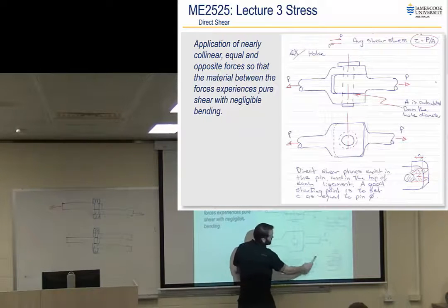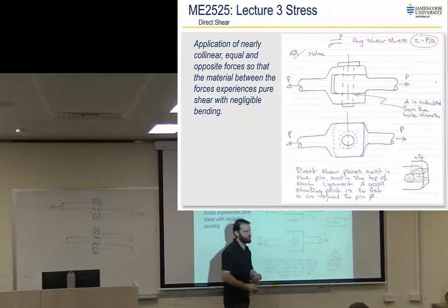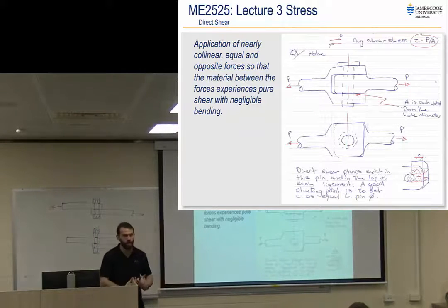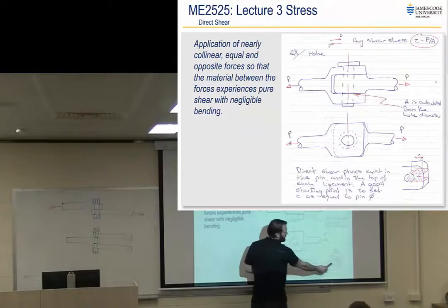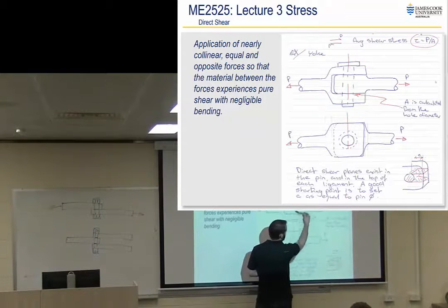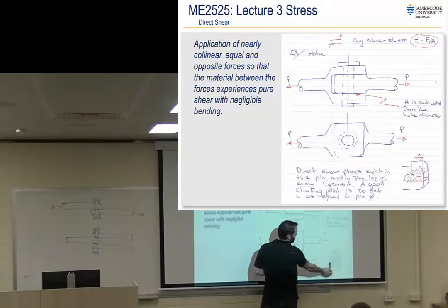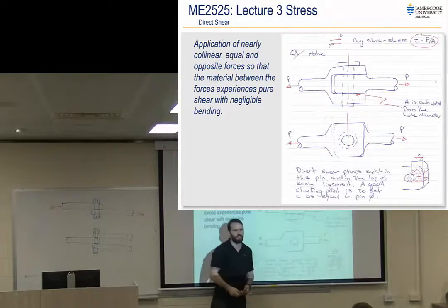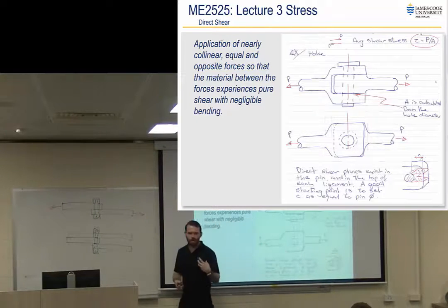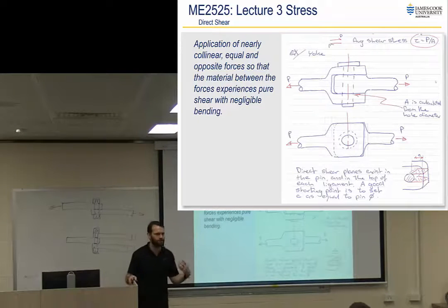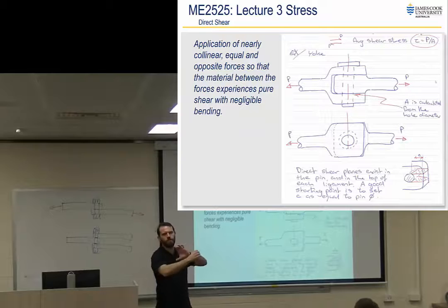And so we were talking about this yoke, and this yoke is basically where the pin's trying to pull itself out of the yoke, or out of the plate, or whatever you're pinning, bolting, etc. And so if we look at one of these end sections, that's the pin, or maybe the central section here, I think this is. So the pin goes through the center of it. We've got shear on each end of the pin, but then that pin wants to pull itself out of the yoke. And so those two planes, the plane at the top and bottom, is basically, if you imagine that this was a really, really soft, potentially almost brittle material, you yank that pin, that's the bit of material that will get torn out when you pull the pin.